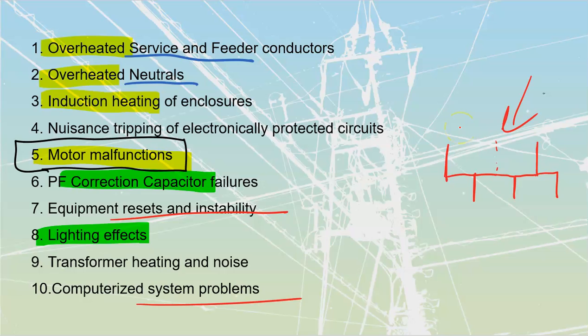If you have induction lighting, particularly some of your older styles of induction lighting that are ballasted and work off of the high pressure inside of them. Mercury vapor is a super old one we don't see a lot of, but our sodium lights or metal halide lights, if you kick one of those out by accident, it takes a long time before that thing is going to come back on. We don't want to see that as well, because then you end up shutting down a lot of your lights for a long time.